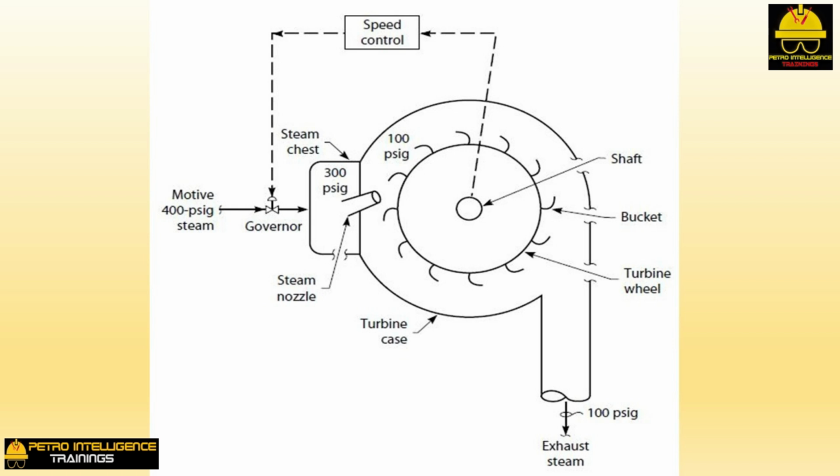This is called an isentropic or reversible expansion. The term isentropic is a thermodynamic expression meaning that the entropy of the steam has not increased. The term reversible in this context means that I could take the high-velocity, 100 psig steam exhausting from the nozzle, run it backward through an identical nozzle, and convert the steam's kinetic energy back into 300 psig steam. An isentropic expansion is also frictionless, in that the ability of the steam to do work is preserved.